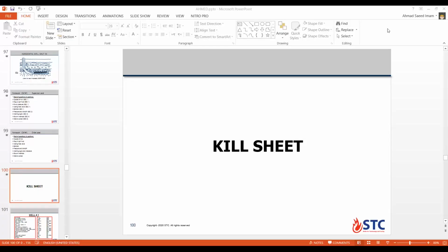So guys, today we're gonna complete our course, second day, talking about the second part of PMP, Principle and Procedure. We're gonna talk about the kill sheet, killing method, ballooning effect, kick tolerance, gas hydrates, and drills or training being conducted in the well site to ensure the crew can effectively recognize and deal with different situations. Okay, so now let's discuss the kill sheet and how to solve a proper kill sheet.